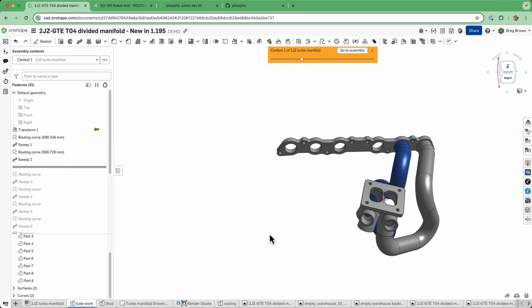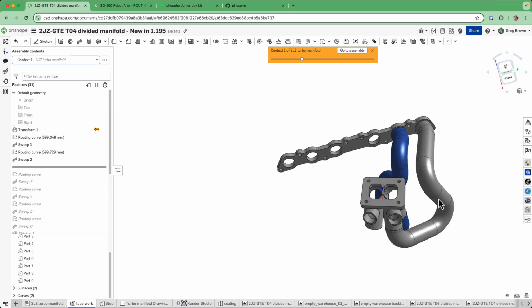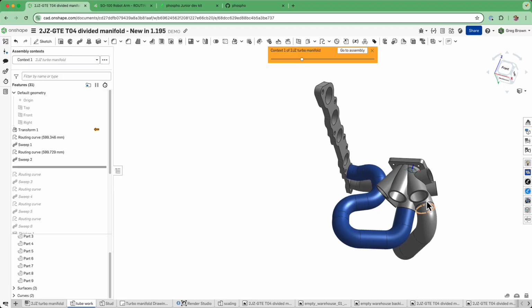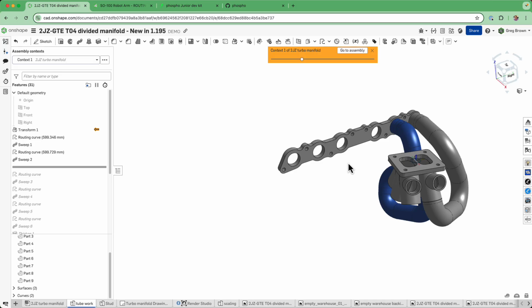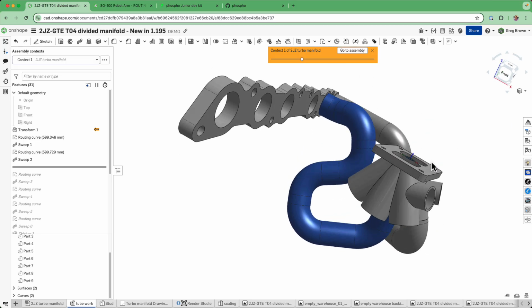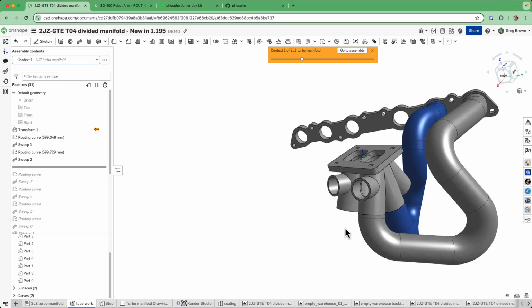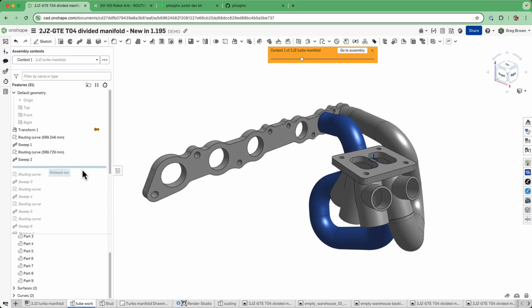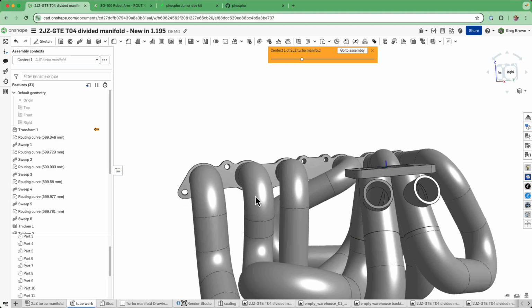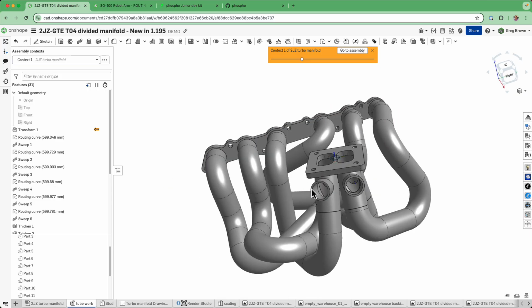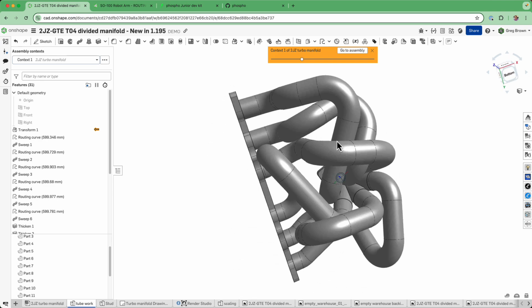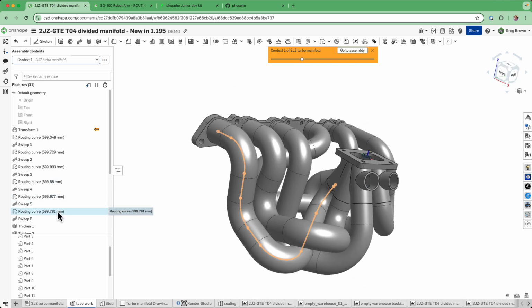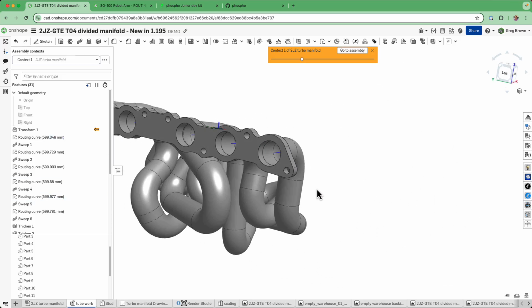I'm trying to hit 600 millimeters as the target. I know the order from down the cylinders and where they are on this merge collector here, and I come up with some schemes to try and get them all to be the right length with the right sort of bend radii, and within a reasonable packaging that we've got. So I did the same thing for those 6 routing curves, and I got it reasonably quickly. It didn't take very long at all, and I got them all within a few tenths of a millimeter of 600 millimeters total. So that's good.